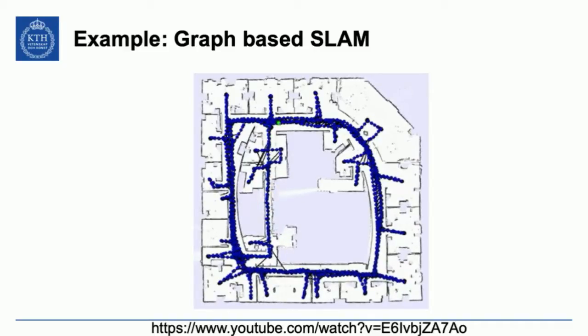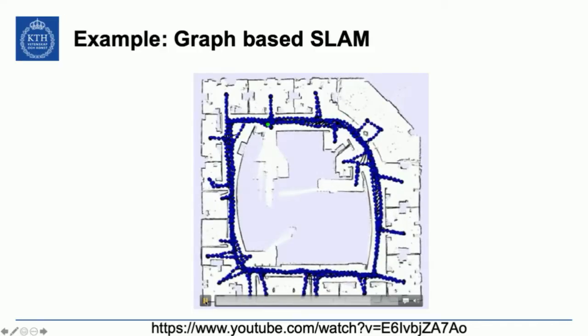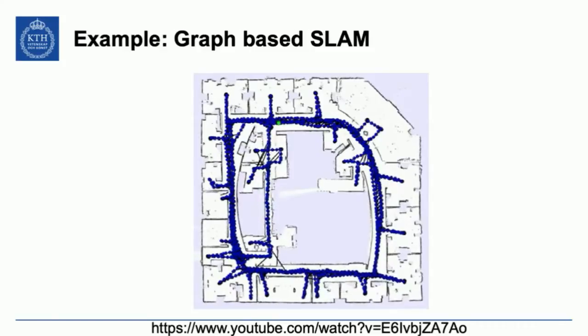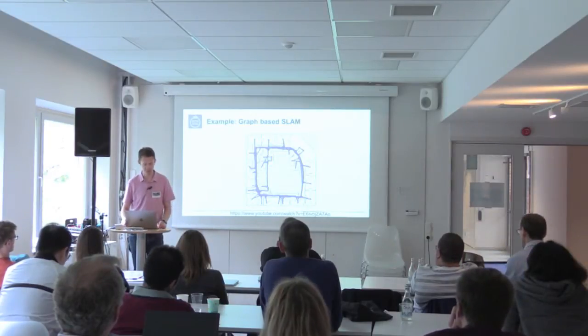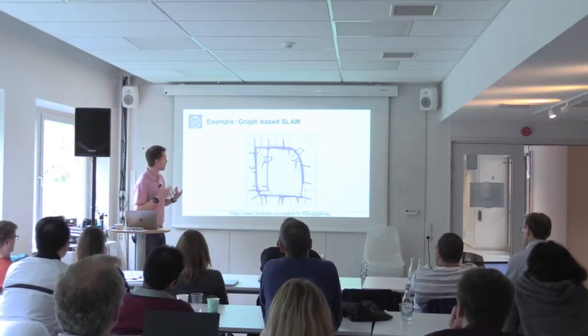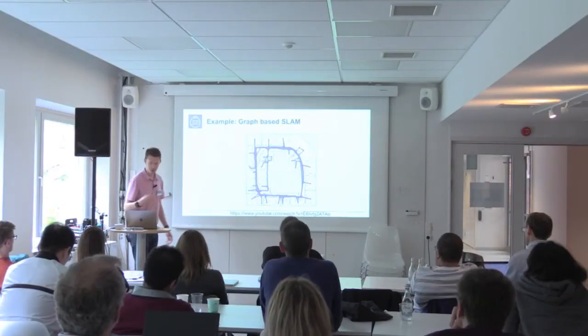So you saw, when the robot goes down here, you see something happening. You see how the map snaps into a better position. This is something called loop closure. Is that good or a bad thing? It's very good. When I implemented the algorithm myself, it was a big rush when you saw that your algorithm actually managed to close the loop